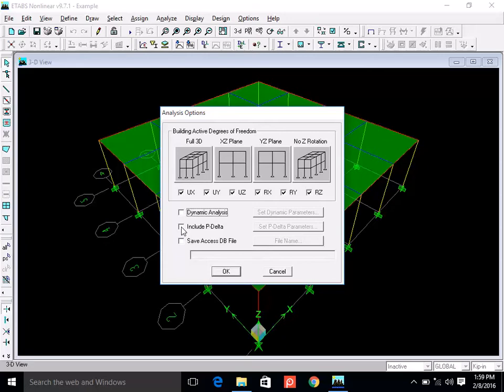So that load into this eccentricity at the center creates an additional bending moment. To take care of that additional bending moment, you have to magnify your bending moment and do the moment magnification. So that is here, include P delta effect. In the shortest way of saying it, P delta analysis is more close to reality, in other words magnifying the moment is more close to reality as opposed to not magnifying moments due to eccentricity produced by lateral loads or by the bending moment.